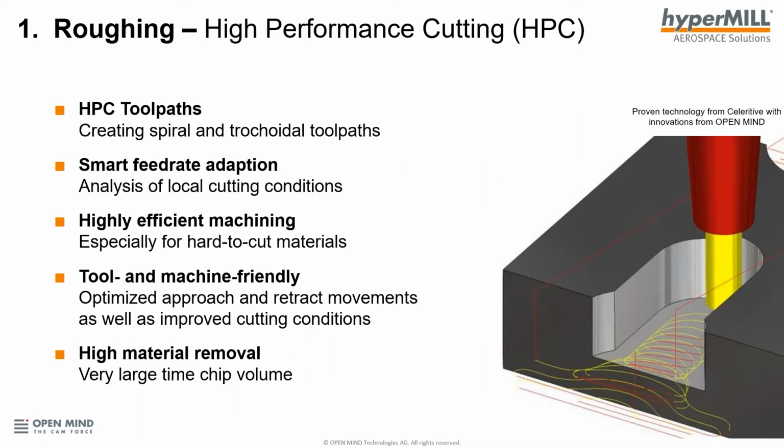So back to max machining. You can see this max roughing cycle is using a trapezoidal type toolpath. It starts on the outside and it's peeling into the pocket, so every cut is repositioning. What's nice is that we're adapting the feed rate. As you come in on the part, the feed rate is optimal for whatever position the tool is in. So you're not adjusting the feed rate because of the worst case conditions. You're adapting as the tool is moving throughout the part.